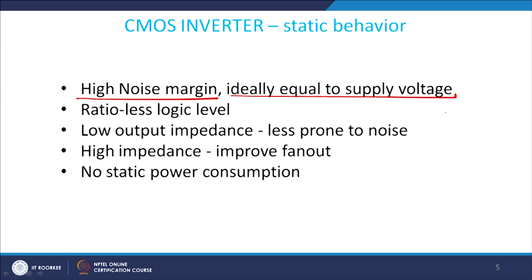So, whatever the supply voltage is, you get that noise margin, which means that a static CMOS inverter, since it is able to pull your output voltage to logic 1, which is equal to VDD, is utilizing the full support from VDD to ground rail. So, the whole range is being utilized by the input level.